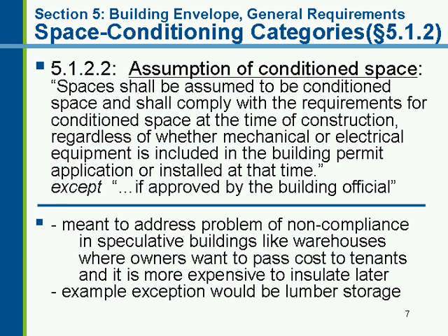Now here's a particular issue that's related to compliance. There's an assumption in 5.1.2 that all space is conditioned space. Let me quote the language here. Spaces shall be assumed to be conditioned and shall comply with the requirements for conditioned space at the time of construction, regardless of whether mechanical or electrical equipment is included in the building permit application or installed at that time.